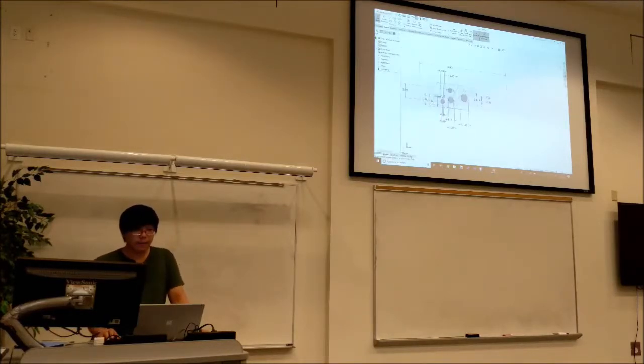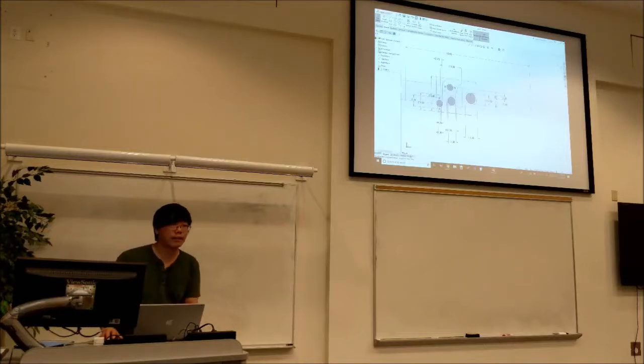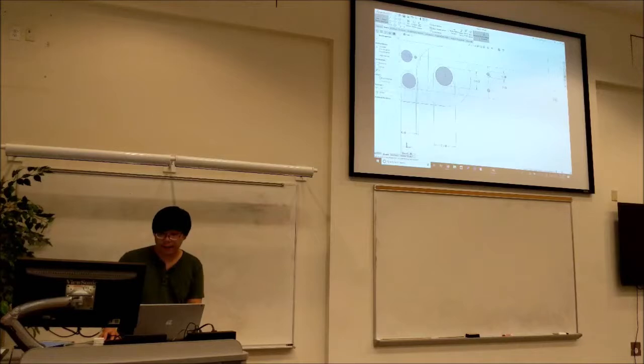And then for the tube, when you do a hole pattern, it's equally spaced across the side, and we want our gearbox to be mounted within the correct hole spacing. So what we want to do is dimension this to this. That's our edge of the tube to the standoff position, or where we're going to mount our gearbox.